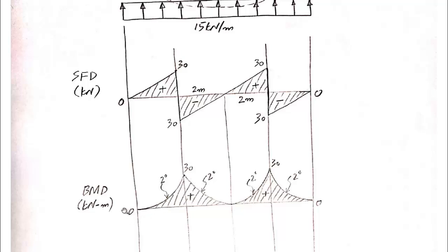Now if we draw a tangent to this point of the bending moment diagram, its slope is 0. And if we draw a tangent at this point of the bending moment diagram, it has some value of slope, which indicates that the slope is increasing as we are moving in the rightward direction. So this is how we decide what the orientation of this curve should be.